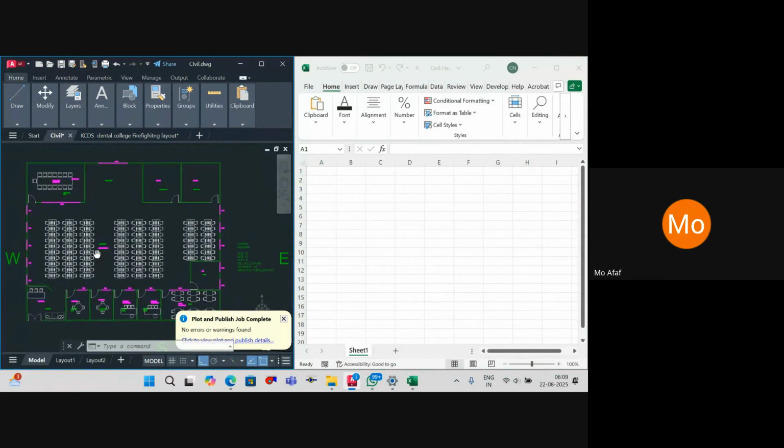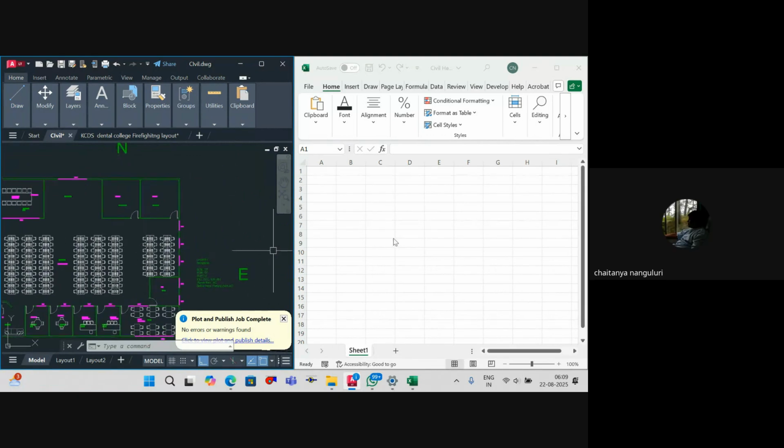First and foremost thing is we have to always calculate your outdoor conditions. Because for every formula, don't you think you were using delta T or delta humidity ratio? So for that reason, you have to calculate the temperature difference and moisture content between indoor and outdoor. Clear?